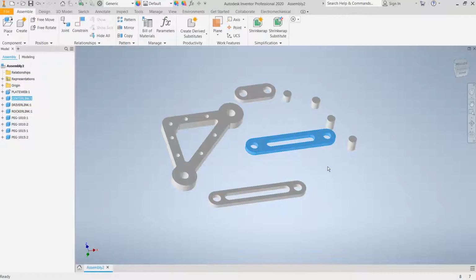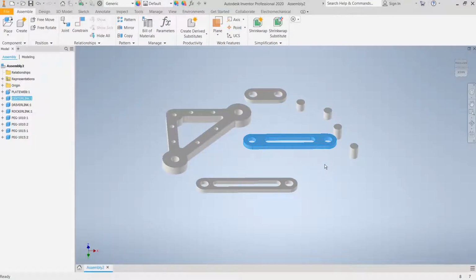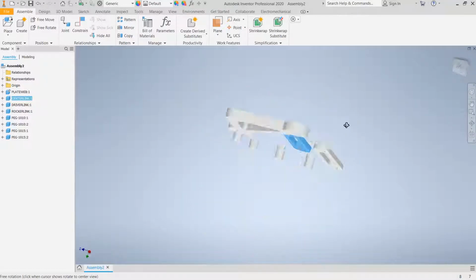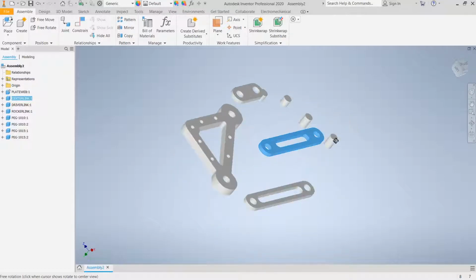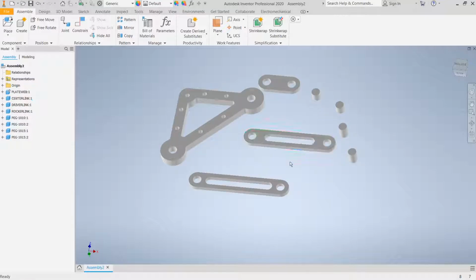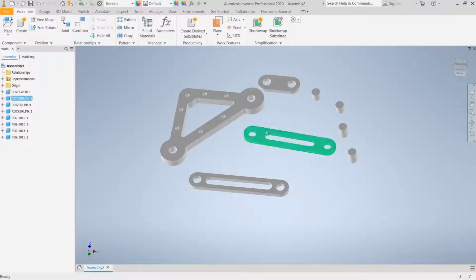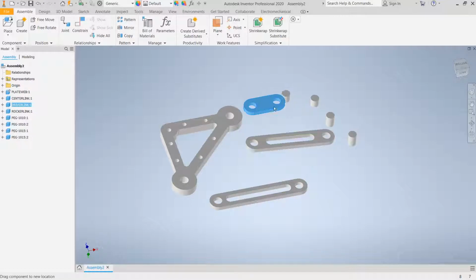Okay. So if you see when I'm rotating, I'm holding down the shift key on my keyboard, and I'm pressing down the wheel on the mouse so you can rotate. But then sometimes you see now it's rotating everything that's here, but sometimes you want to rotate just one component. So you press on that component and you press G, letter G on the keyboard, and then you can just rotate a single component, right? And then you just escape. Right. So now we're going to create relationship.